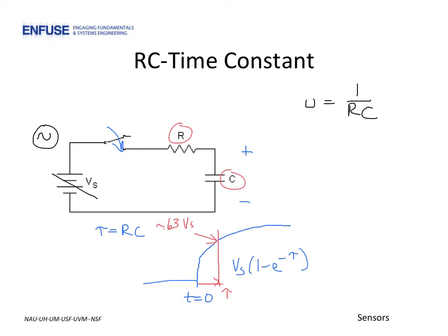For example, for one particular value of R and C, the output voltage might be sinusoidal like that, but as R or C increases depending on the type of change, the output voltage in magnitude would decrease. This type of conditioning circuit can be used not only with resistive-based sensors, but capacitive-based sensors as well.